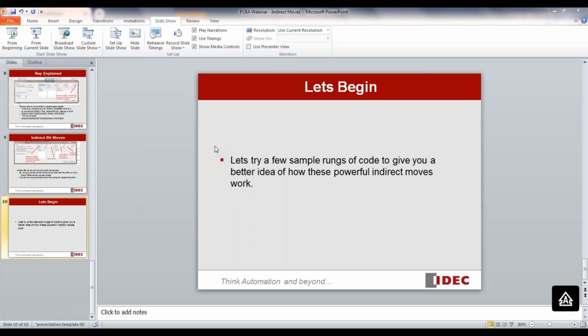So, like, one box would come in and it would turn it 90 degrees, then a box would come in and it would send it to one side of the conveyor system, and another box would come in and it would send it to the right side of the conveyor, and then the fourth box would flip up 90 degrees, and it would load a line of boxes like that, and then it would push the boxes out. After it got the number of boxes on the layer, it would move that onto the top of a pallet, and then a sheet would come back down and it would move another layer of boxes and position them